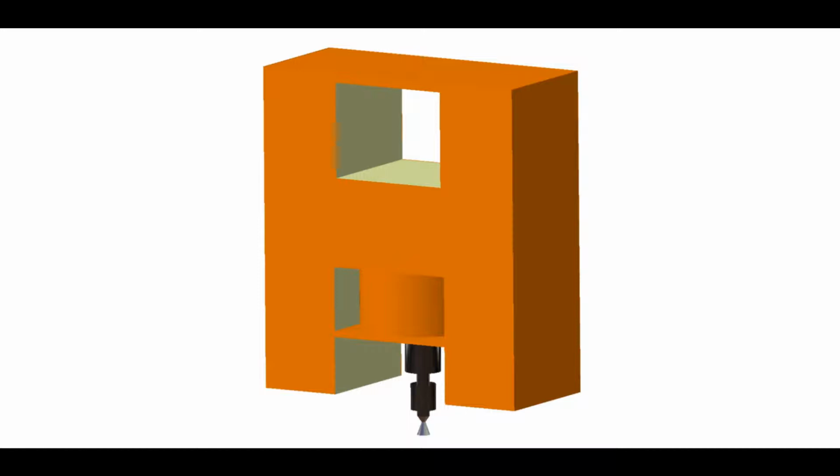However, after consulting a specialist, we decided to underestimate this point. On the other side, the electric thrusters also had a major problem. That is, because of their very tiny thrust force, they require many time to achieve their destiny. In this project, that has a lot of importance because the CubeSat would spend a big fraction of its lifetime orbiting around Earth and crossing the Van Allen radiation belts, which is very harmful to the electronic components if they are not very well protected.